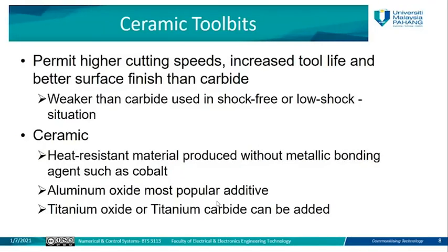We have the automatic tool changer, or ATC. This automatic tool changer, which includes the box of different tools, will list the types of tools used with this CNC machine, and also show, for example, the hardness of each tool and which materials are preferred for ceramic tools or for high speed steel. It depends on the type of your workpiece.